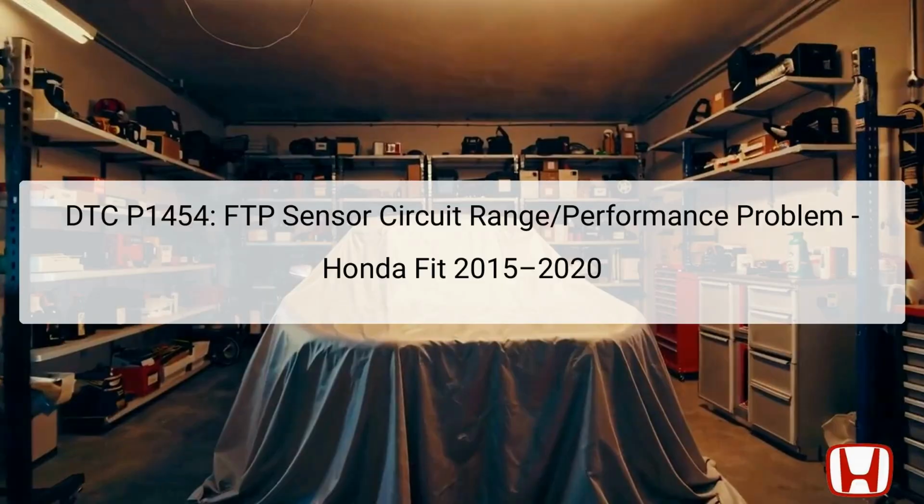The diagnostic trouble code, DTC P1454, indicates a problem within the fuel tank pressure, FTP, sensor circuit, specifically related to range or performance issues. The FTP sensor plays a crucial role in the evaporative emissions control system by monitoring the pressure inside the fuel tank. Its location is typically found in the fuel tank or connected to the evaporative canister.